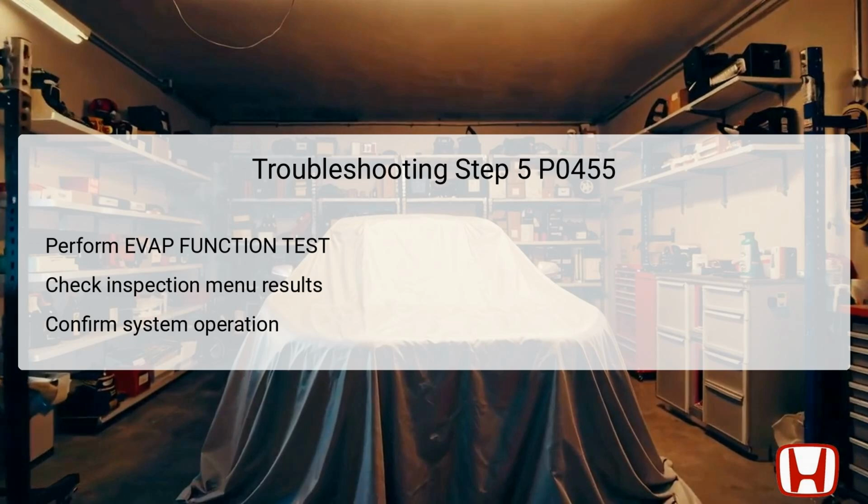needed. If the results yield an OK response, it may point to an intermittent failure, meaning that the symptoms may not be currently present but could recur under different conditions. In such a scenario, examining connections and terminals related to the fuel tank pressure, FTP, sensor, and various valves becomes crucial for identifying potential issues. Conversely, if the test results indicate a fault, it necessitates moving forward to the next troubleshooting step.